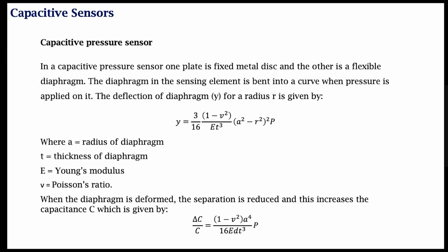It depends on what is the range of values of displacement that you are interested in, and that depends on where you are going to place the sensor, what are the general ranges of displacement that happens in that particular part of the body, and so on and so forth. That is how you can maximize sensitivity and minimize noise and make the system affordable.